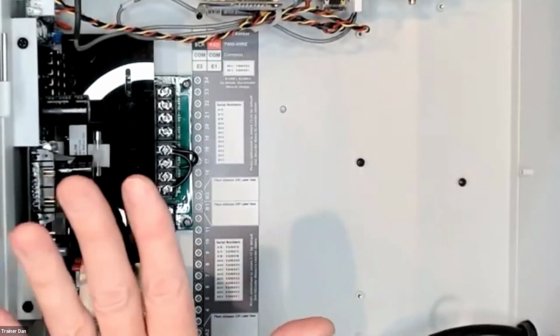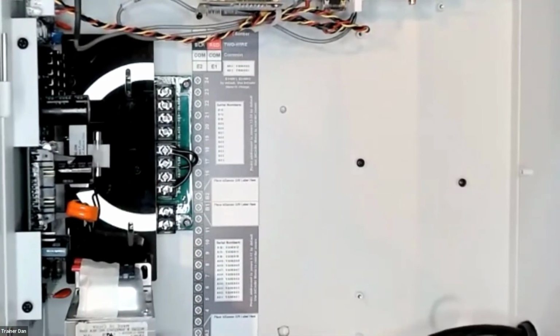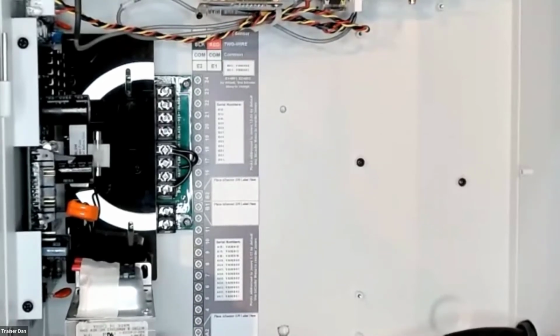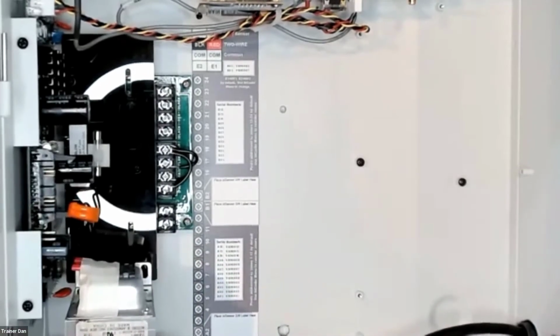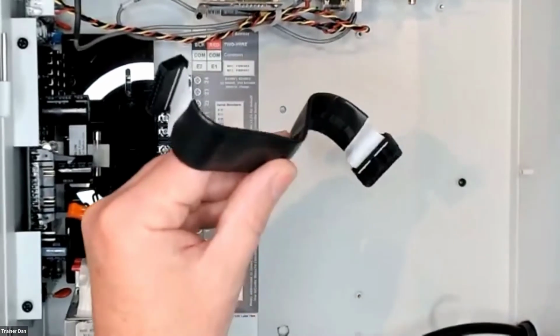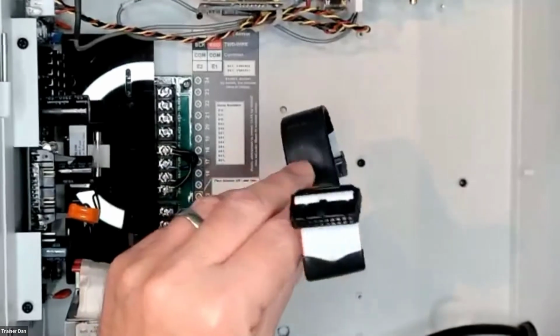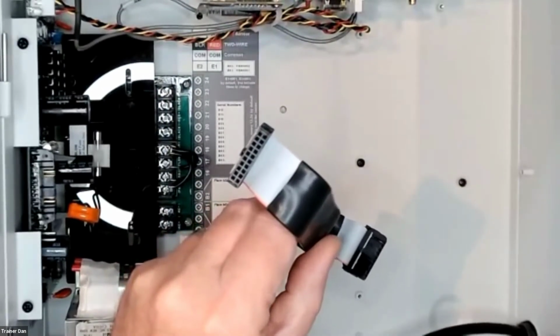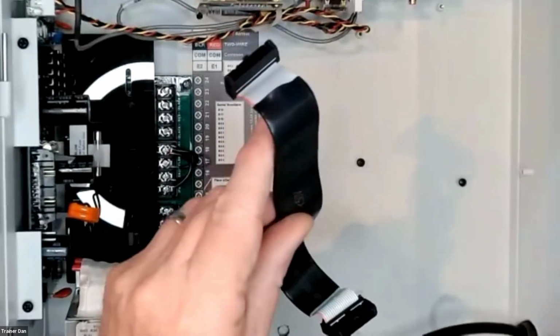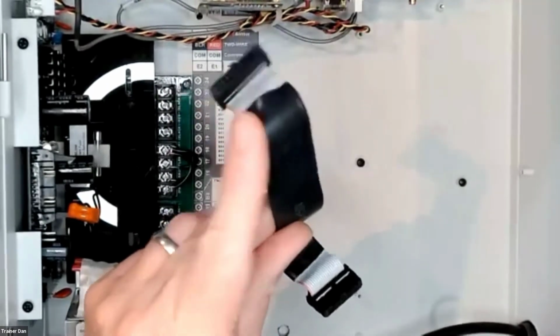Very cool. While you're there, and this is an afterthought, Dan, but the ribbon cable for the display is also part of that connection, right? When should you, if ever, disconnect the ribbon cable? Yeah, I already disconnected my ribbon cable because I knew I was going to pull off the front panel. I only want to disconnect this ribbon cable after the power supply has been shut down.